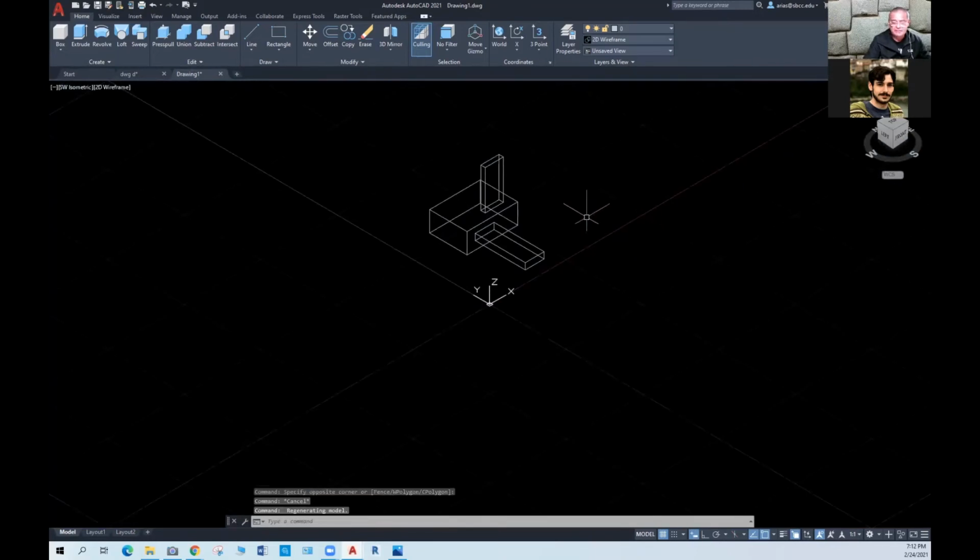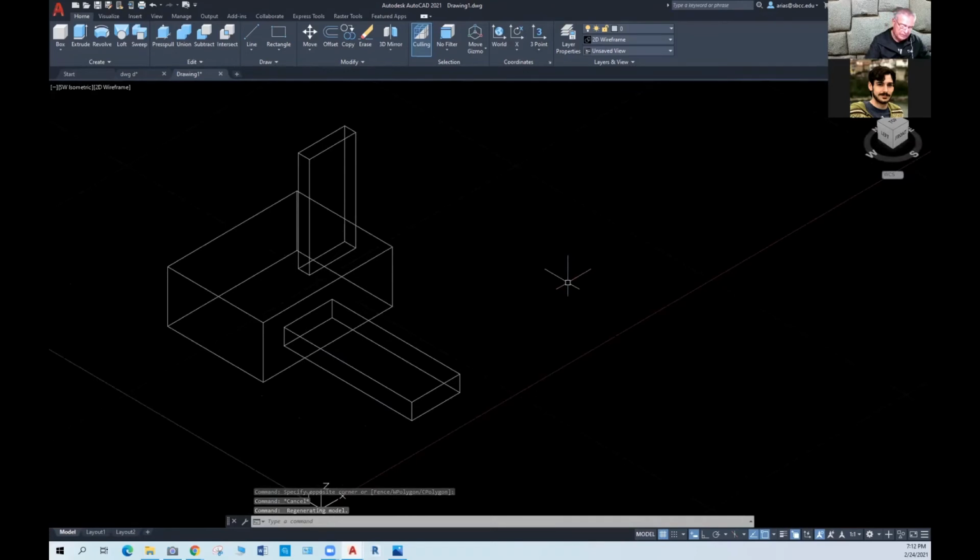And so that's a fundamental concept in creating geometry in 3D in AutoCAD, because you are going to be using 2D tools to generate 3D content all the time. And to be able to place the object where I want it to start from, you need to make sure that you control the UCS properly. And that's it. Okay, so let's move on.